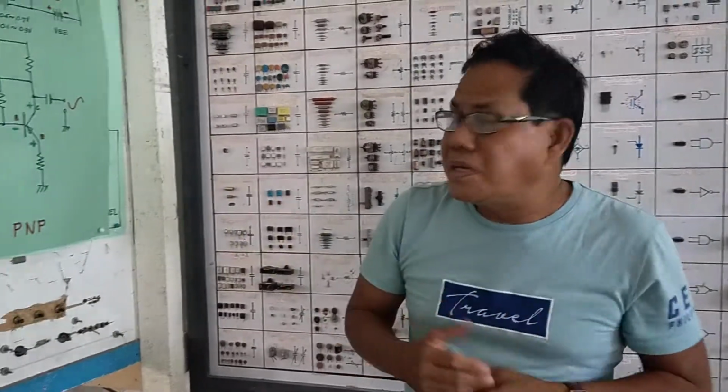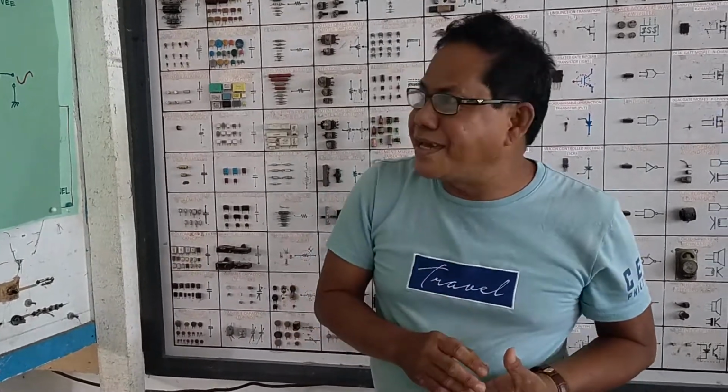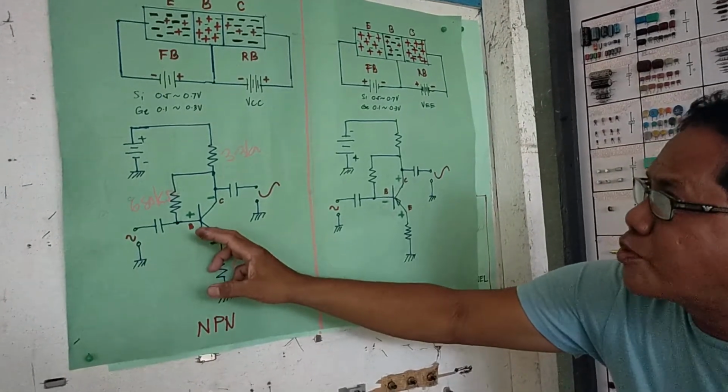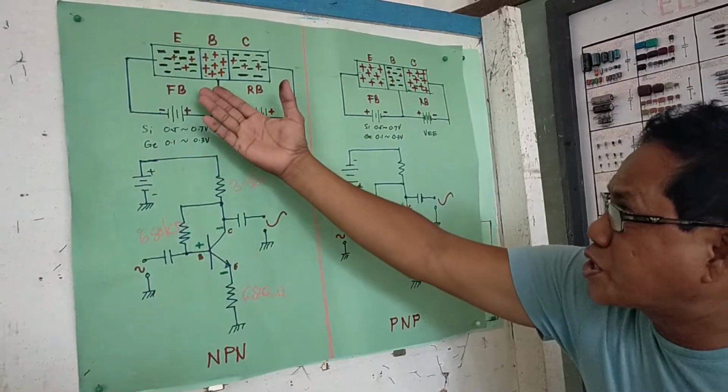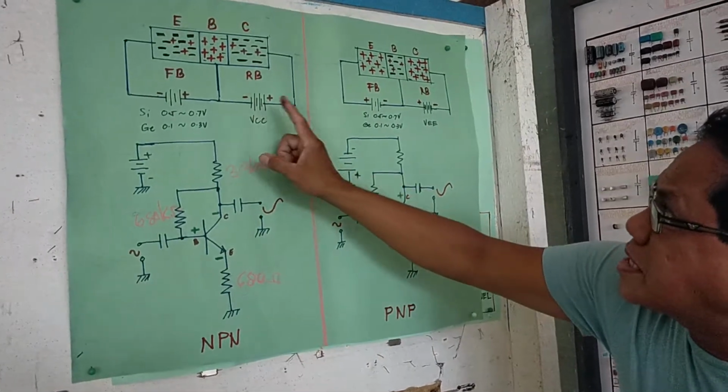So, that is why germanium is seldom used because of its cost, medyo mahal, plus the availability of that material, germanium, is limited also. Okay. So, base-emitter again is always forward biased based on this construction. Whereas the collector-base junction here is always reverse biased.